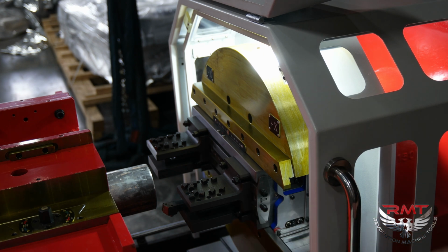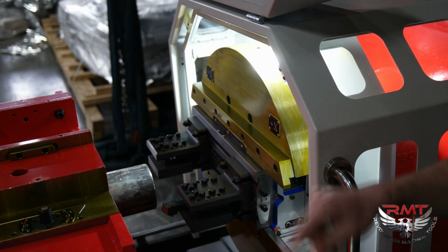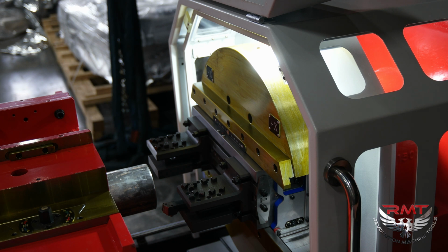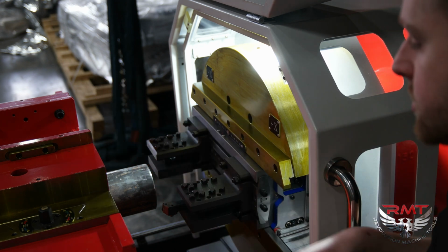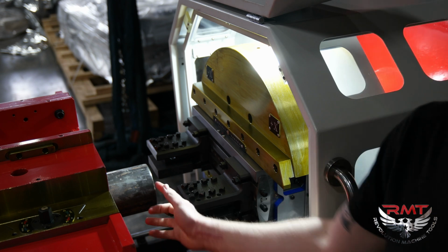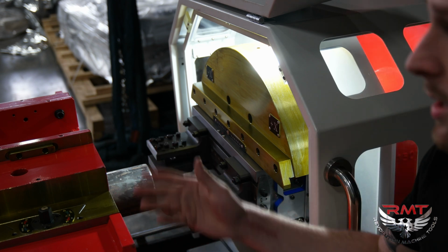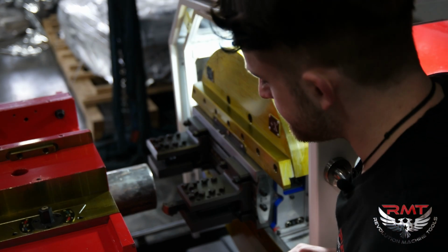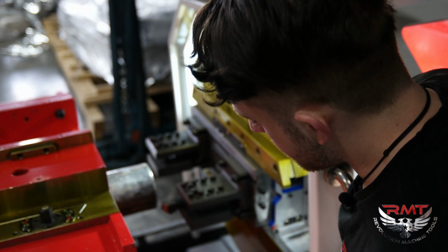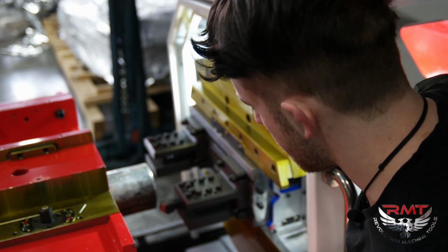Now, also remember, the spindle rotates, so don't think of positive and negative as like right and left, so to speak. You just have to know tool 1 is negative and tool 2 is positive to go deeper. But I'm just going to kind of eyeball this close.